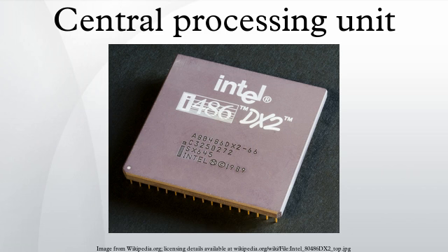In effect, integer size sets a hardware limit on the range of integers the software run by the CPU can utilize. Integer range can also affect the number of locations in memory the CPU can address. For example, if a binary CPU uses 32 bits to represent a memory address, and each memory address represents 1 octet, the maximum quantity of memory that CPU can address is 2^32 octets, or 4 GB. This is a very simple view of CPU address space, and many designs use more complex addressing methods like paging to locate more memory than their integer range would allow with a flat address space.